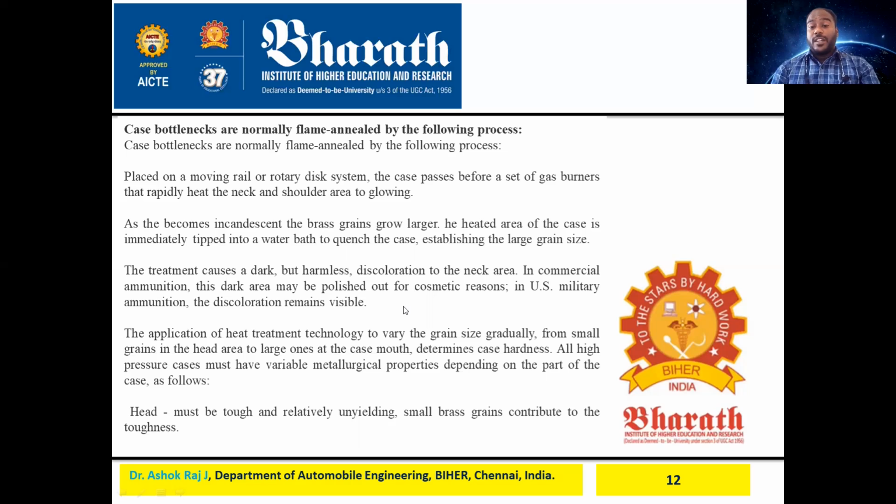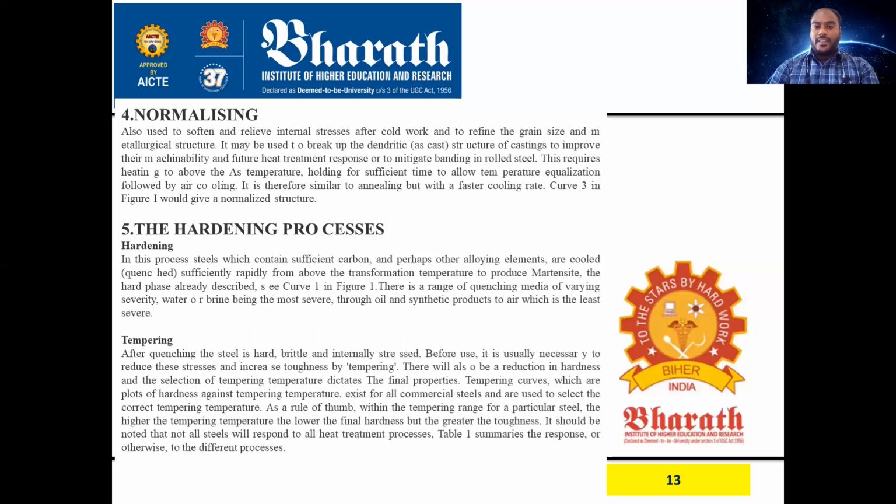The application of heat treatment technology to vary the grain structure gradually, from small grains in the head area to large ones at the case mouth, determines case hardness. All high pressure cases must have variable metallurgical property depending on the part of the case. The head must be tough and relatively unyielding; small brass grains contribute to the toughness. This is the reason.